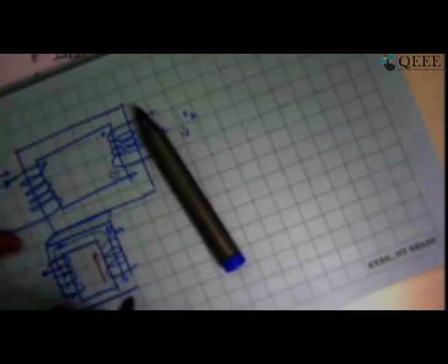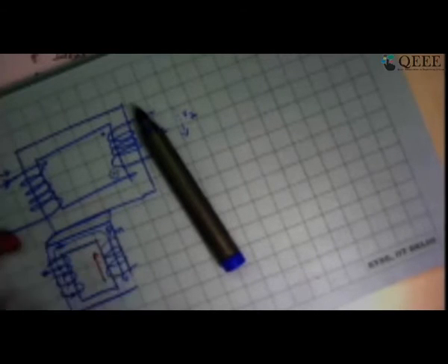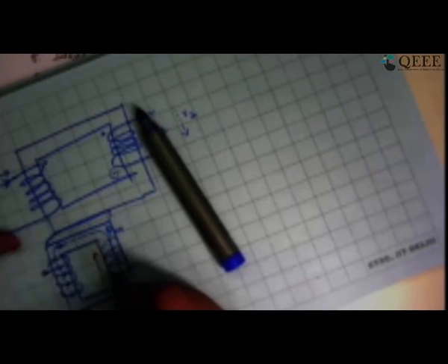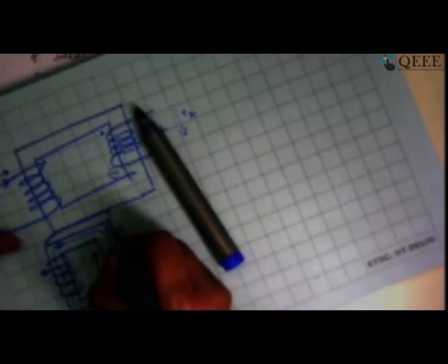Downward sense was the original flux due to the mutual coupling and due to the primary current. So the secondary current should actually flow in such a way that it is going to induce a flux in the opposite direction. So let us say if the current is flowing like this, it is flowing like this and so on. And that is what is creating the flux in the opposite direction. Clearly, this is at a higher voltage than this.